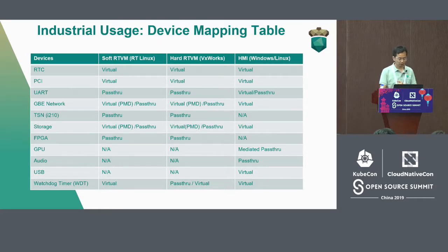And with virtualization, you could achieve the real-time effect. And then about FPGA, it might be needed for some mathematical processing in the industry. Usually for FPGA, we would have it pass through RTBM, and then directly access FPGA. And we also have some customers asking whether it could be shared so that they would support multiple simulated PLCs visiting the same FPGA. But now we do not have a clear answer to that. If you want to virtualize FPGA, it's not that difficult, but if you want to make it real-time, it is quite tricky. So we may need a further design on FPGA.